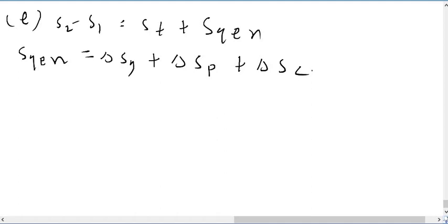So now we expect entropy generated to be greater than 0 if the process is irreversible. So the change in entropy of copper is equal to 0. Why? There will be no interaction with the copper. There is no interaction with copper since it is kept in what? Adiabatic membrane. So entropy generated of copper is 0. So what of piston? The entropy generated of piston is also 0. It's mechanically adiabatic actually.